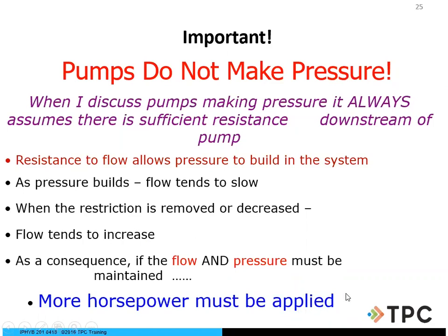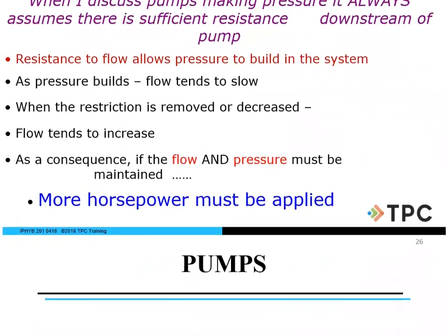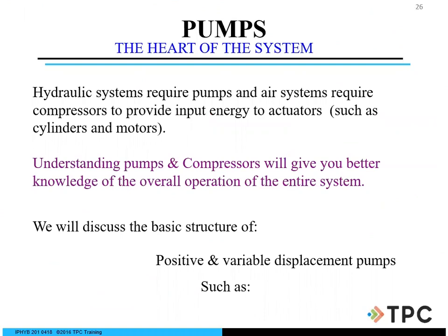That's why we need to look at our system before anything else. What size motor, what size pump do we need? How much horsepower is required for our hydraulic system? Once you do know those things, again, you're able to troubleshoot a little bit better.